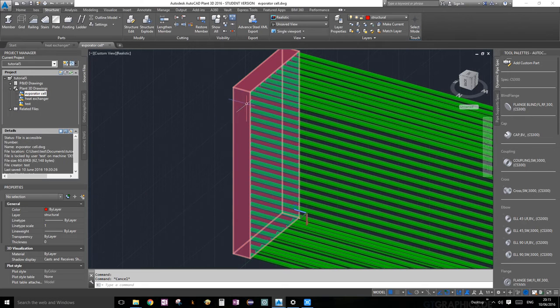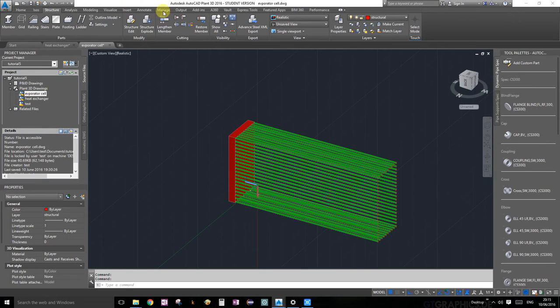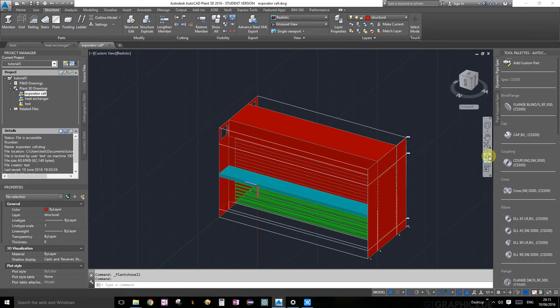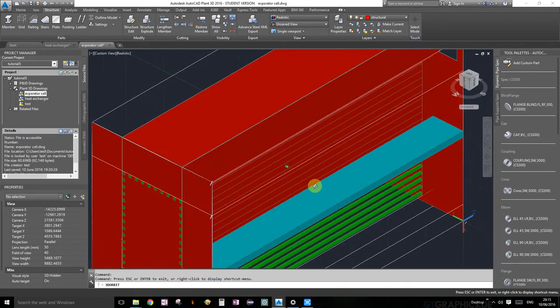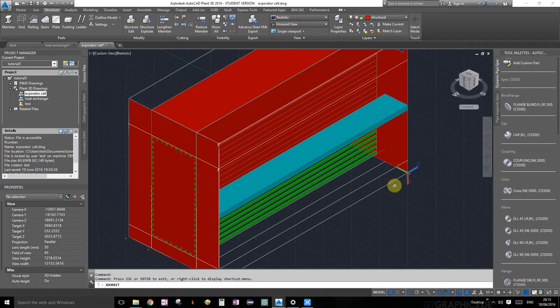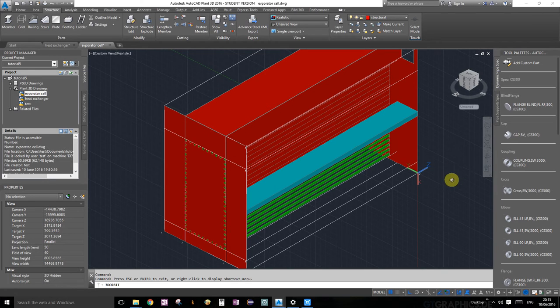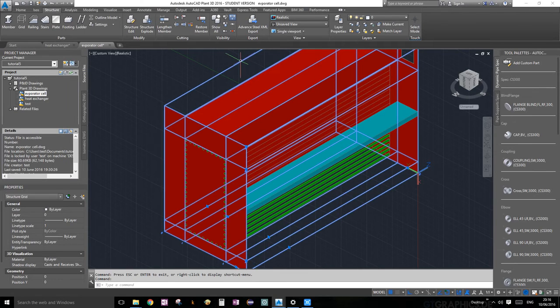Okay, now it's going into the bulkhead, so the steam would come through here, turn around and go back. Okay, so let's go back and show everything else again. Alright, that looks pretty good to me. And the next thing we need to do, we need to put a plate here that's going to separate the steam, that's going to stop the steam from just going through and getting to the distillate area. We want it to come through here and go through the pipes around the bulkhead and come back out. So that's what we are going to do right now. Let's go ahead and do that. Okay, so hide everything else except for your grid again.